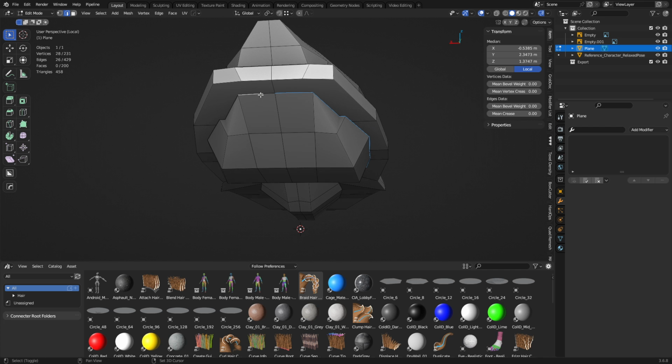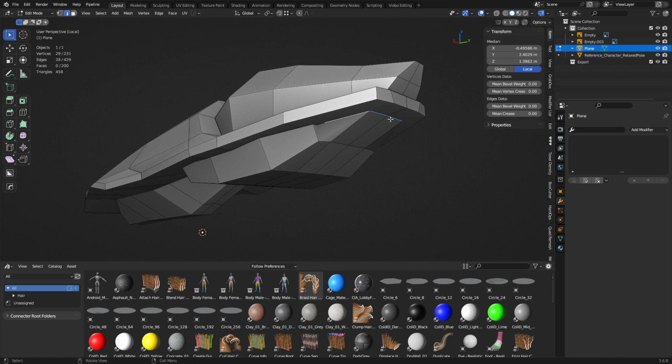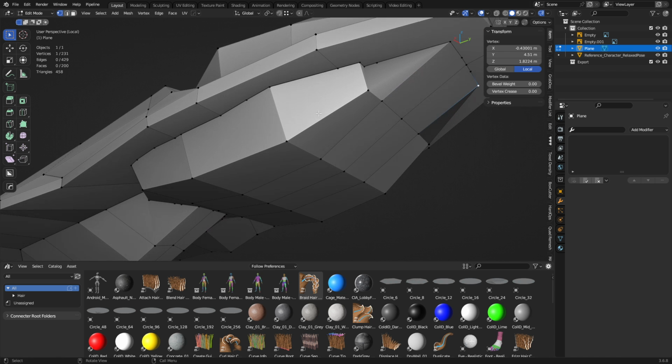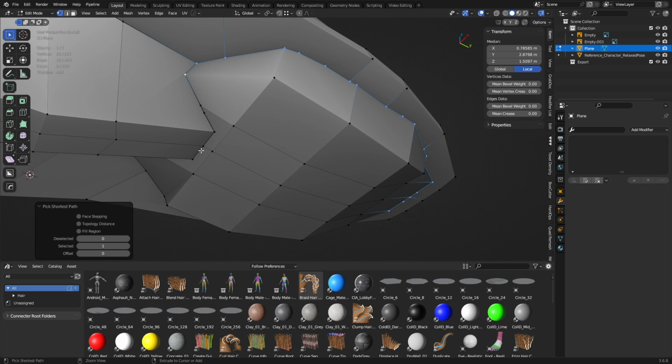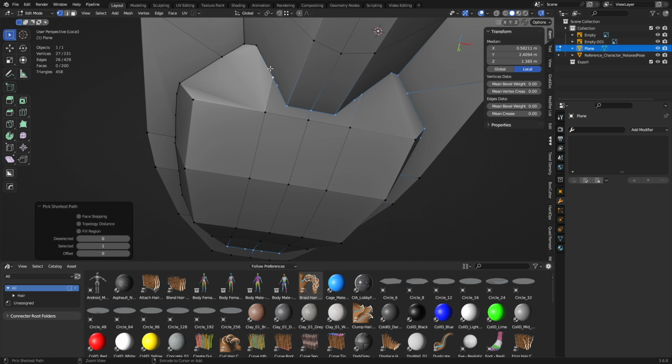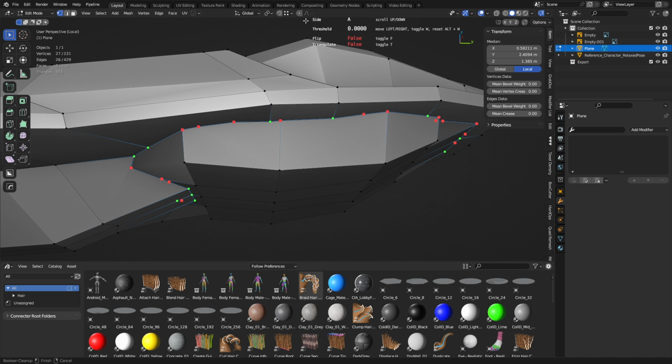Using the shift click, alt click, or you can do shortest path selections. Actually, we're not having much luck with shift clicking and all that, so we'll just do control click and select all the way around the border here. Hopefully this gets everything I need. You can use Mesh Machine and do a Boolean cleanup, okay? And so you mouse wheel up and down, you can pick which ones are going to stay good and which ones are going to collapse.